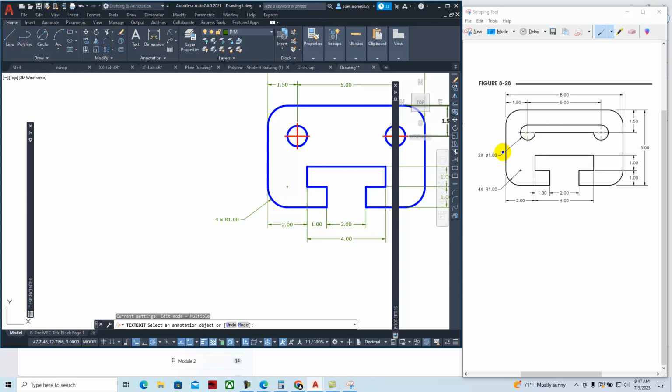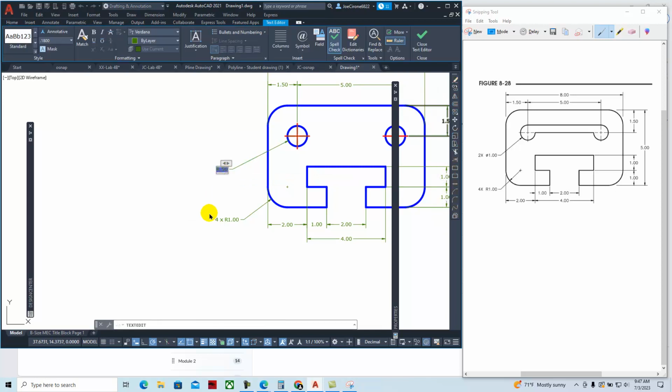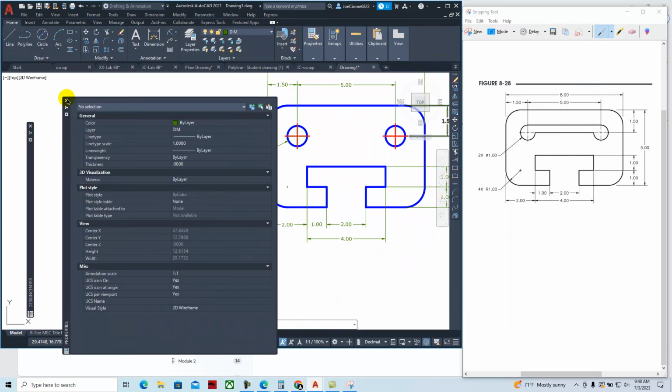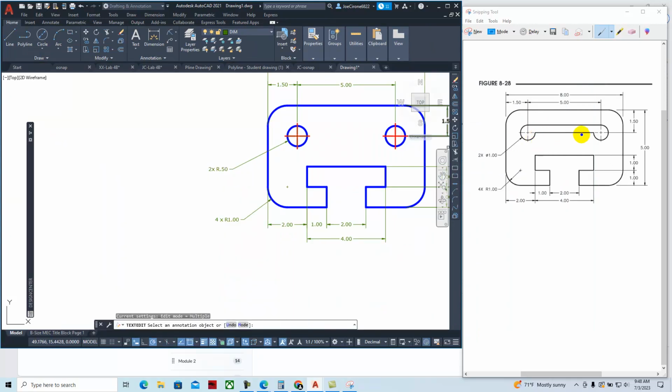And then we'll put in our other radial dimension. So we'll come back here to radial dimension, we'll select that, we'll bring that over, we'll double click on that, bring that over, 2x, green check mark. And then I noticed as I'm looking at it that I missed some of the slot geometry right here. And so it's got a slot from halfway to the top here.